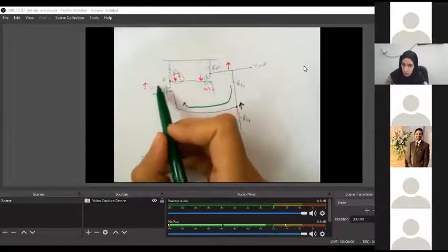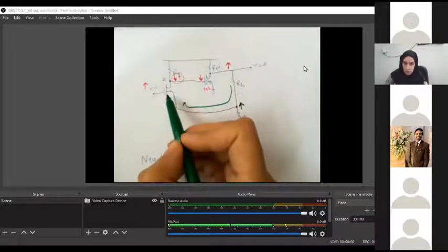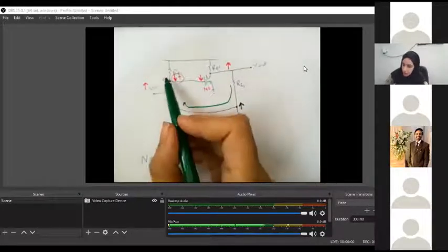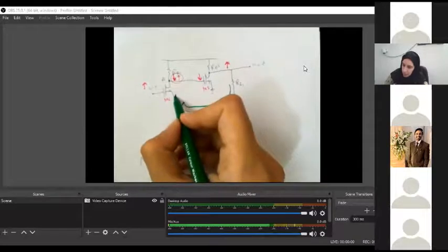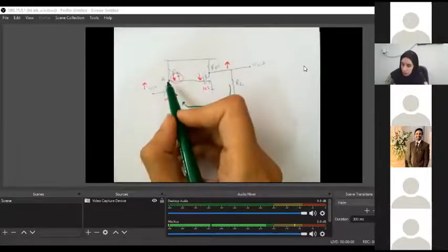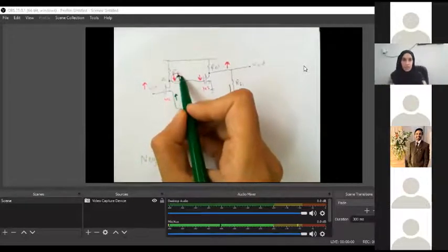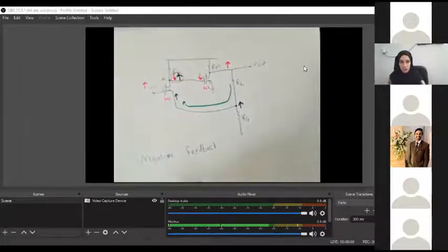Therefore, this is going to be a common gate amplifier. The input is applied at the source, taking the output from the drain. Now, if this goes up, what's going to happen to the drain side? It will also go up. Why? Because the common gate has positive gain.